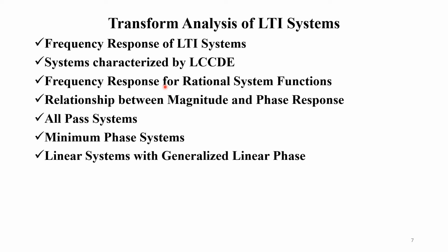In particular, if the magnitude response is given and the number of poles and zeros are known, then there are only a finite number of choices for the associated phase. Similarly, if the number of poles and zeros and the phase are known, then within a scale factor, there are only a finite number of choices for the magnitude response.